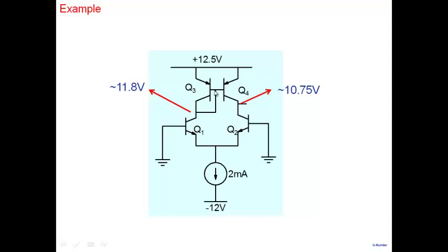So instead of applying a voltage here, a simple short between base and collector allows us to bias this particular differential amplifier with a fairly stable bias point, with both transistors working in active mode. But obviously you can see now that the circuit is no longer symmetrical. This one, base and collector are shorted together. So this one is like a diode and its resistance is very small. On the other hand, base and collector are separate here. The small signal resistance of this particular one would be large. So what happens is you develop voltage gain here and you don't get much voltage gain here.